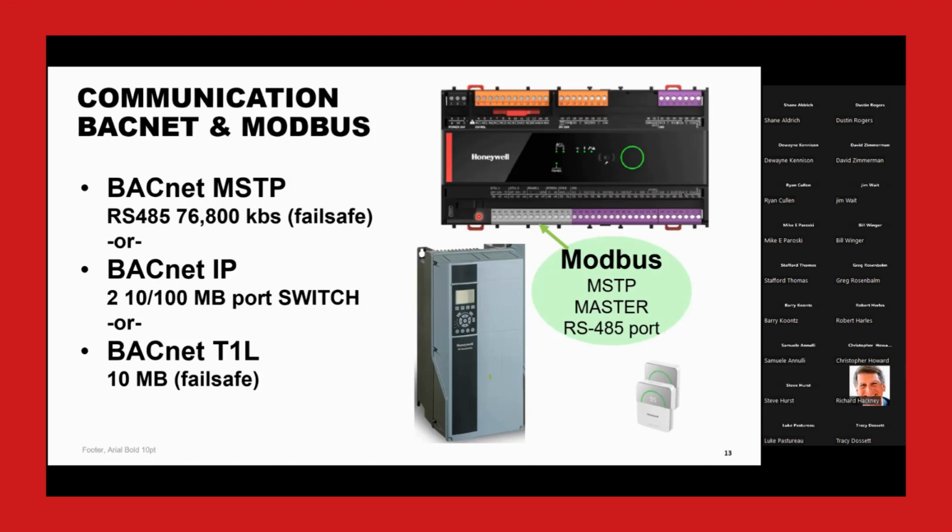And instead of using my I/O to get 3 or 4 data points in and out of the VFD, I'll talk Modbus and maybe get 30, including things like the fault code or the kW, turn the VFD into a submeter and get the kW and kWh off of it. So if you can talk Modbus downstream to the VFDs on a VAV air handling unit, you're probably way ahead of the game. And if I can use Modbus in lieu of the physical I/O, then maybe I don't need the more expensive large controller. Maybe I can get away with a small version of the unitary controller and also be way more competitive.